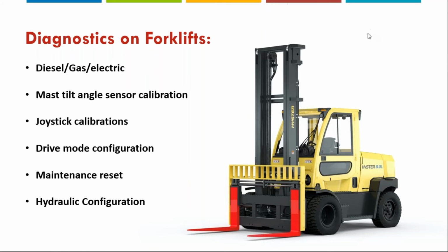Well, on the forklift side, as I explained before, we will be able to do diagnostics on diesel, gas, and electric machines, and we will be able to perform some special functionalities like tilt angle calibration, joystick calibration, drive modes. As you may know, on material handling equipment, we have modes like eco, performance, that will change the speeds and all of that. And also we will be able to do hydraulics configuration.